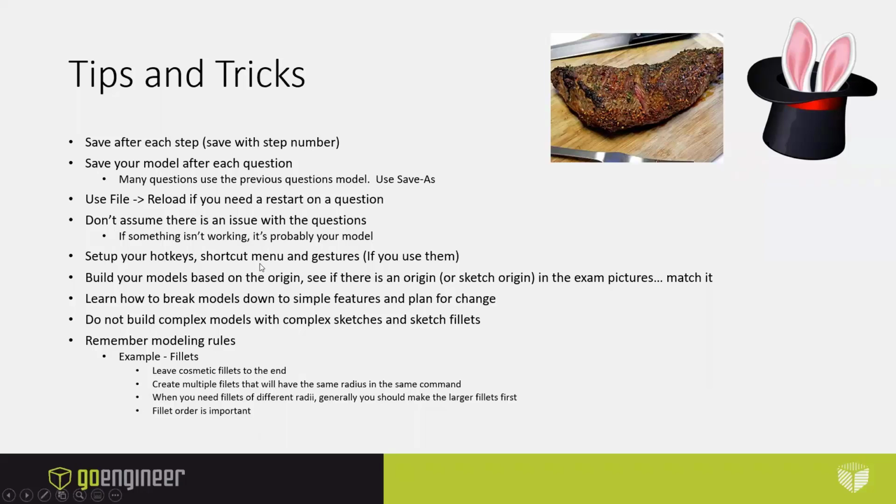Set up your hotkeys, shortcut menu, your gestures. If you use them, don't try to start just using the shortcut keys if you're not comfortable with using shortcut keys. If you've never used shortcut keys, while you're taking the exam is not the optimal time to learn how to use shortcut keys. Build your models based on the origin. If you see an origin in the exam pictures, match it.